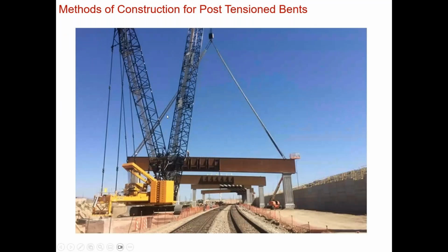This is an example of a bent, but unfortunately I didn't find a photo for a concrete bent, a post-tensioned concrete bent, but that's the same idea. It's similar to the steel straddle bent when you have it manufactured in shop and then arrives to the site, and basically you have cranes like this that lift the bent from the two ends and place it on the columns. That's why this procedure can be limited to certain lengths and weights for the members.